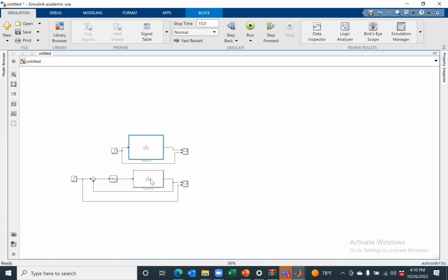Now what you do is you add proportional, you add derivative, and you add integral term only when you are close. If you add integral term when you're far away, that will lead to integral windup. Okay, so integral term is never used when you are far away from the set point.